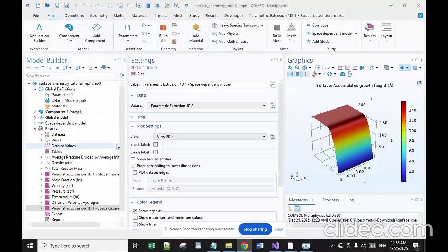The choice of source gas depends on the thermal stability of the substrate. For instance, aluminum is sensitive to high temperature. Silane deposits between 300 and 500 degrees centigrade, dichlorosilane at around 900 degrees centigrade, and TEOS between 650 and 750 degrees centigrade, resulting in a layer of low temperature oxide.